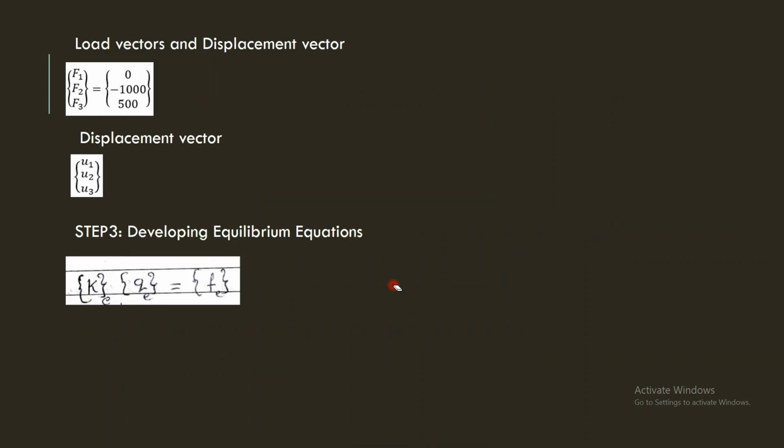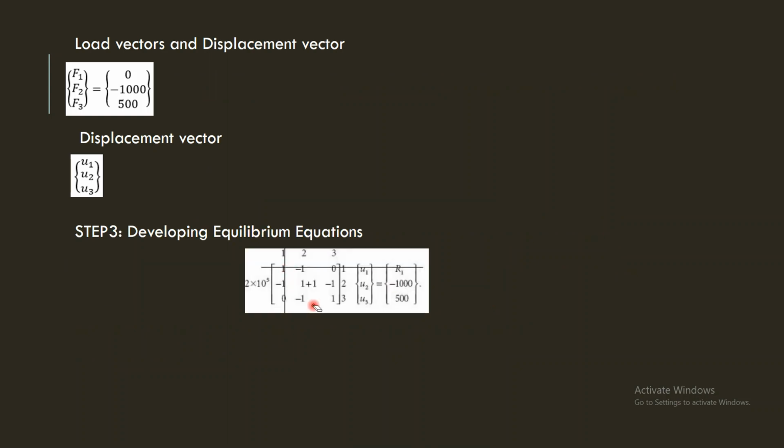One more concept of a stiffness matrix is that it is a symmetric matrix. That is, all the contents above the diagonal should be the same as below the diagonal. If you find these positions, you can easily substitute them in the lower diagonal values. But the diagonal values will differ, so please take care of that.